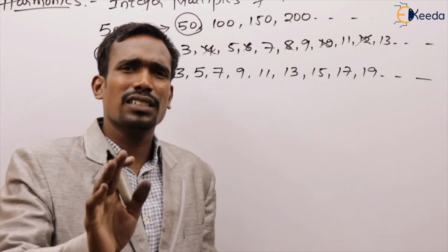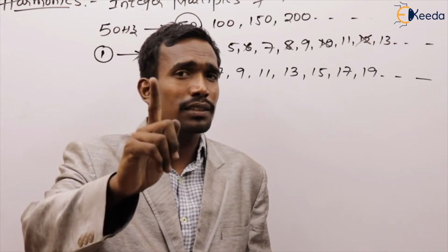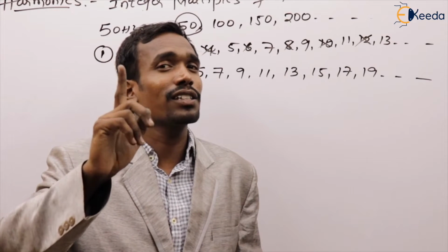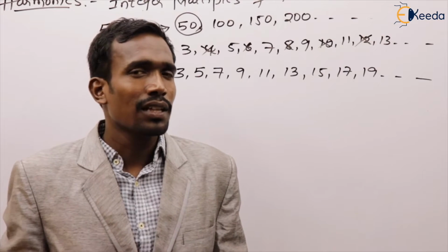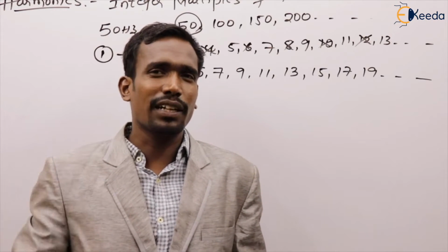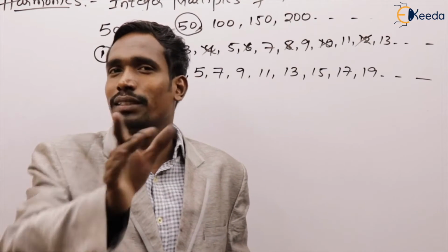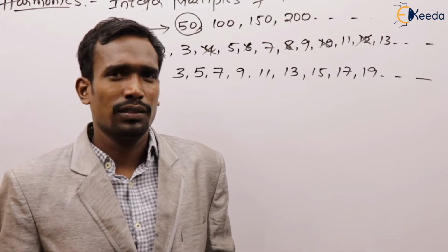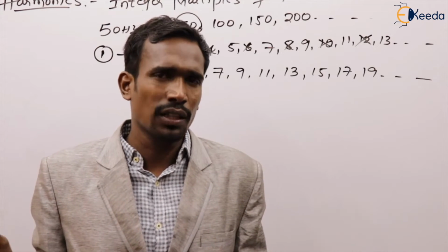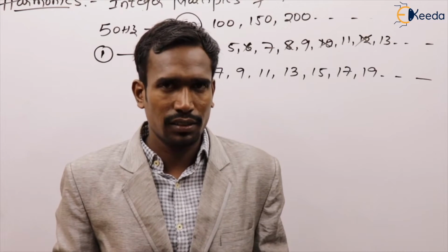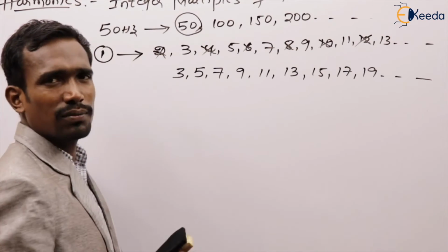In our electrical subject, we saw even harmonics in only one place, in the magnetic inrush currents of a transformer. At that place, the waveform is not symmetrical to the x-axis. That's why in magnetic inrush currents, second harmonics are present. Mostly we don't see even harmonics anywhere else. Otherwise we have only odd order harmonics.